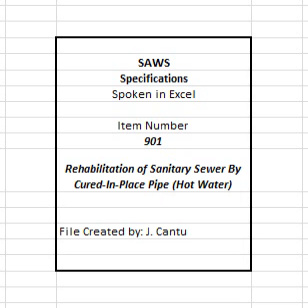9. Soil depth, maximum distance in feet measured between the crown of the pipe and the highest point of soil cover over the length of continuous CIPP section. 10. The liner shall be designed for a minimum 50-year service life under continuous loading conditions.